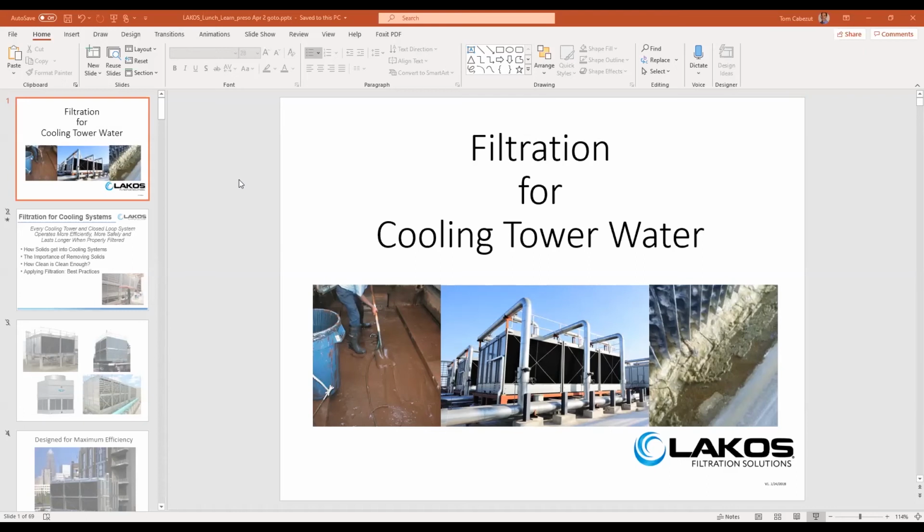And as Tom mentioned, utilize the valve packages and put in a system sized for one tower and sweep multiple towers. We don't need to be sweeping 24 hours a day to have a pristine basin. We can get away with a third of that or even less possibly.